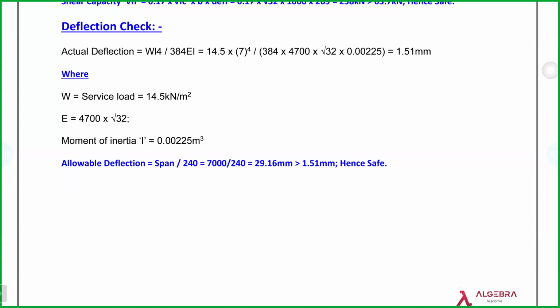I'm going to ask you a question again. In two-way slab, now you understand what is two-way slab, right? In two-way slab, you do have 4 layers, right? Bottom 2 layers, top 2 layers, isn't it? In Dubai, this is how we used to follow the reinforcement of the slab, isn't it? Whatever you say is B1, B2, T1, T2, right? Assume I'm going to have a shorter direction, longer direction, and top longer direction, shorter direction, correct?